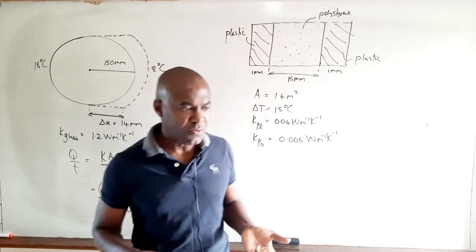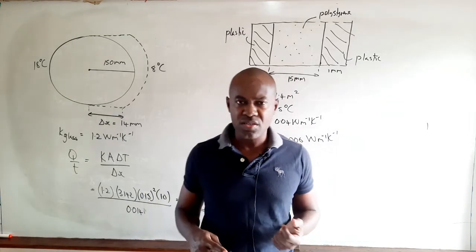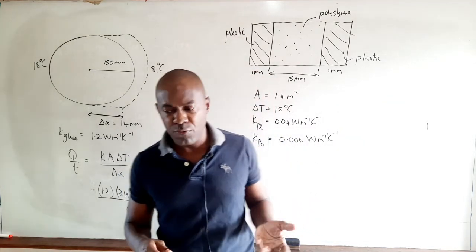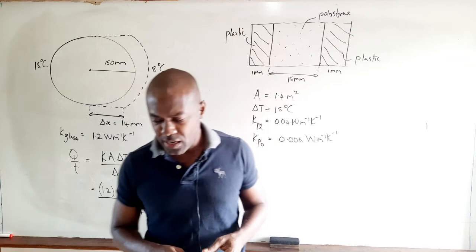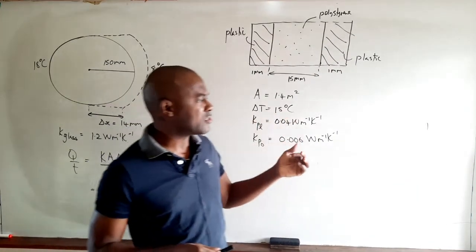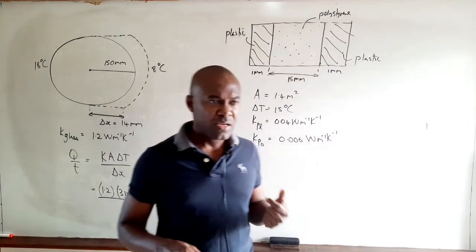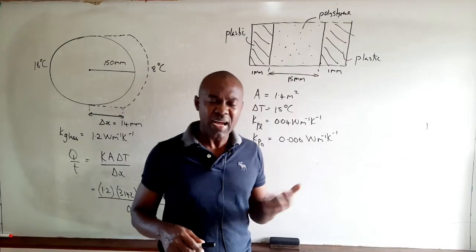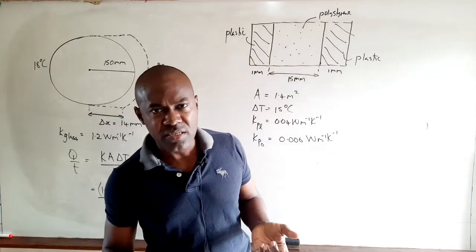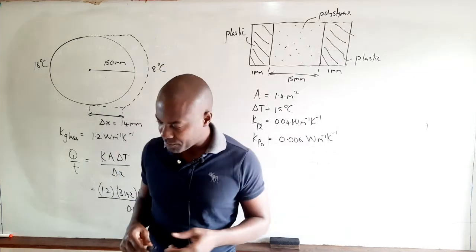Heat flow is more or less analogous to current flow. So we can find an expression for the thermal resistance of each layer, and because we're treating them as conductors in series, their resistances will add, similar to electrical resistances of conductors connected in series.